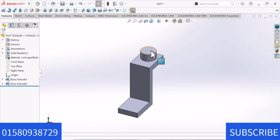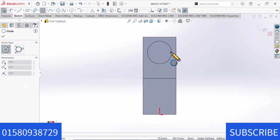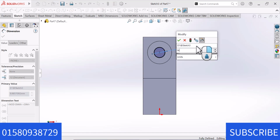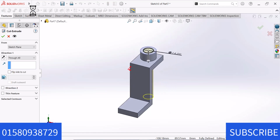Now go to this face and sketch. Now draw the circle from circle point, give the value 14. Okay. Now go to Feature and select Extruded Cut. Okay.